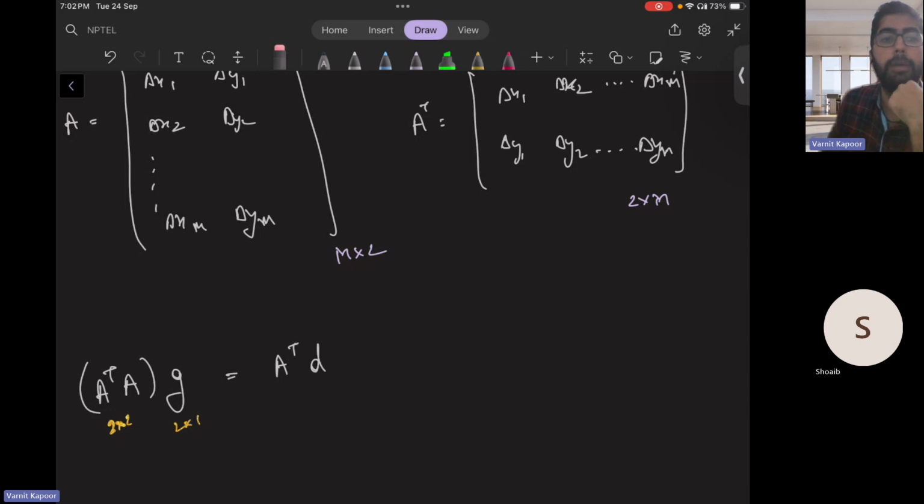The other thing is that we are going to look at how you implement, or program, a solution procedure for solving a diffusion equation on unstructured meshes. It doesn't matter whether it's an orthogonal mesh or non-orthogonal mesh. As long as you have an unstructured mesh, you can implement it. And what is the way to do it? Another thing we are going to do today is to see that boundedness is not guaranteed even if the source terms are absent, in the context of unstructured non-orthogonal mesh. Why is boundedness not guaranteed? After finishing that, we will move to how we program the diffusion equation on unstructured mesh, and whether it is the same way as we do for the structured mesh or something different. All this we will look at, and maybe we can code these things if time persists.